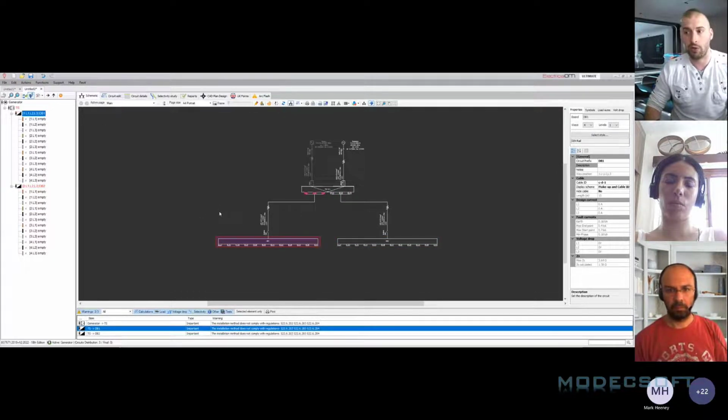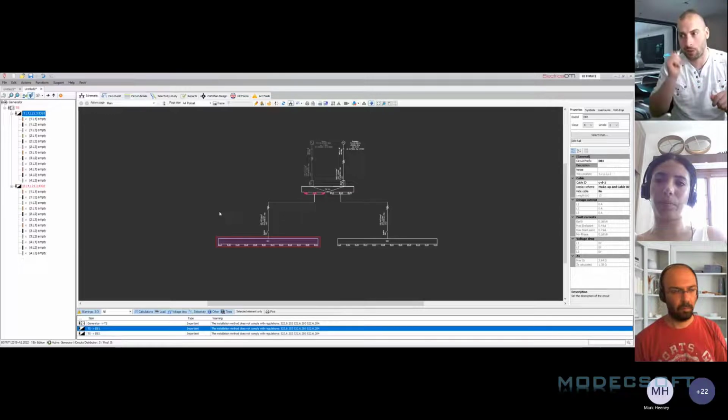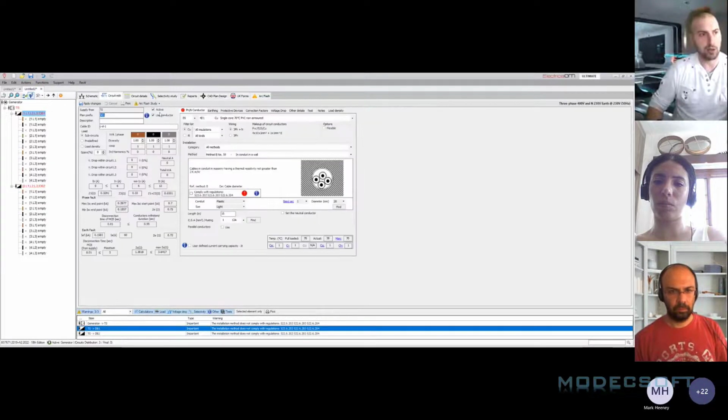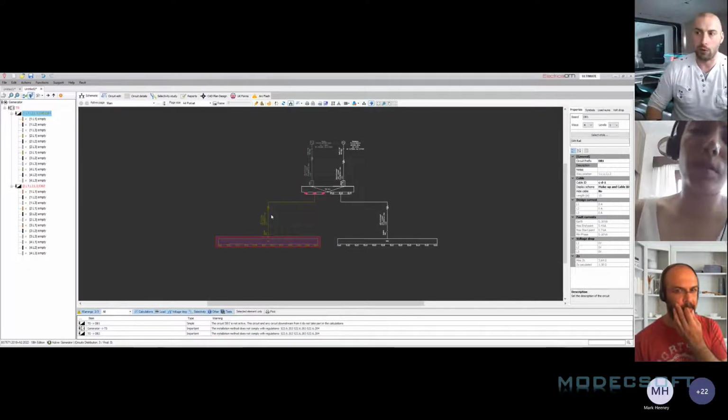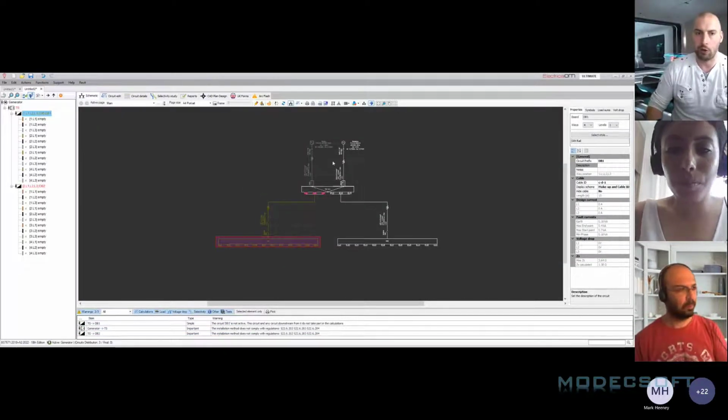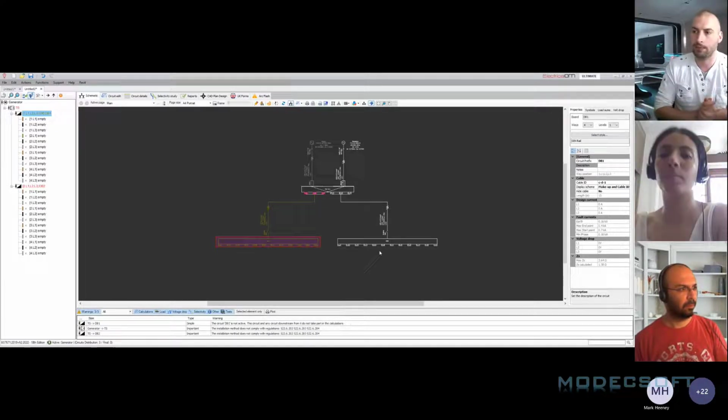We've got something called operational scenarios in the software where you can set different scenarios up and then quickly switch between them. We're not going to have time to go through it today, but here I can say, under this generator supply, this is a non-active supply, so now this will be omitted from our reports as well, because we're only supplying this part of our network. So effectively that is our installation.